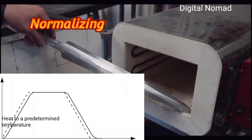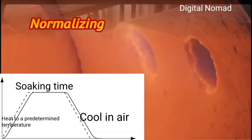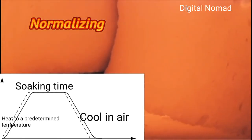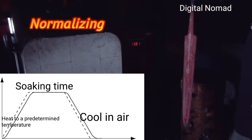Normalizing. Normalizing is defined as a heat treatment process where a material is heated to a pre-decided elevated temperature above its upper critical temperature, held at that temperature for a certain period of time, 10 to 20 minutes, and then allowed to cool freely in the air to reach room temperature.